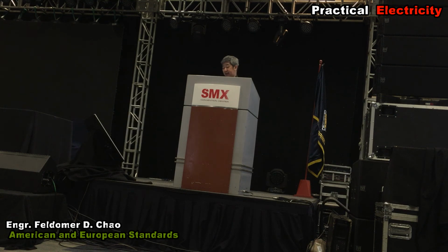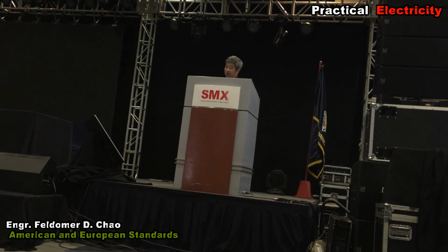Impulse test. This is the test that the American ICEA doesn't have compared with the IEC, meaning you're subjecting the cables to a test of their resiliency against surges. Here, the IEC requires 10 positive and 10 negative impulse voltages. On the other hand, the Americans are trying to ensure that the cable will be reliable.